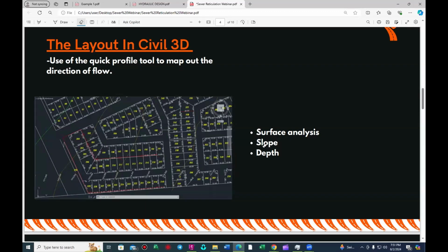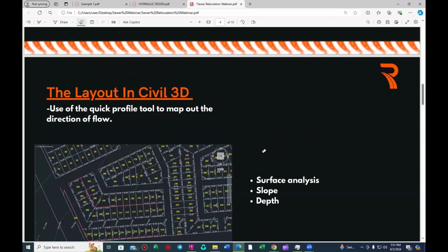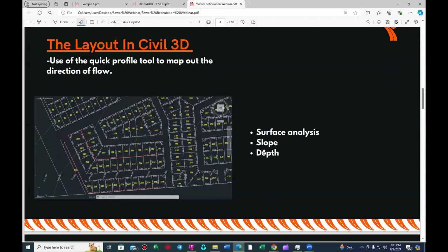We're not going to introduce a pump in any of the system, unless we want to do a pipe main where we're now lifting the sewer, probably pumping it to a treatment plant. But if it's just a regular sewer system that's collecting sewer from houses, we do not need pumps. In fact, pumps are expensive. Yes, there are instances where we use pumps, but sewer systems are gravity pipe systems. So they are essentially functioning under gravity. So gravity has got what slope? You guys should know this, right?